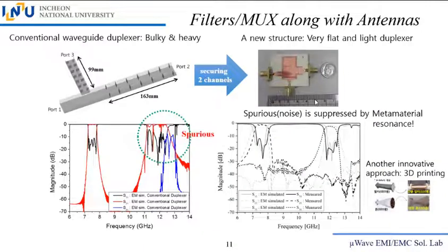And my students have designed and developed a very handy and light filter structure, extended like the duplexer here, very compact compared to the classic waveguide structure. We can deal with the design of a duplexer in the frame of a waveguide, but here a spurious problem occurs, then other techniques should be applied there to suppress this field.